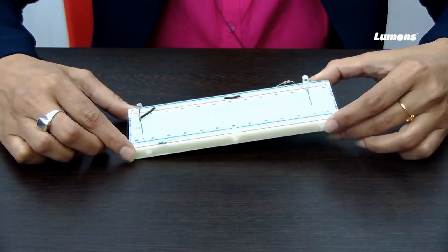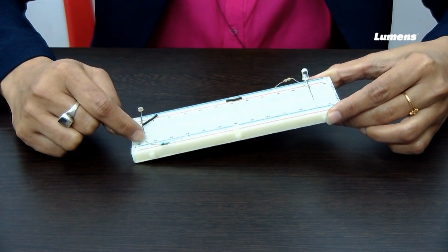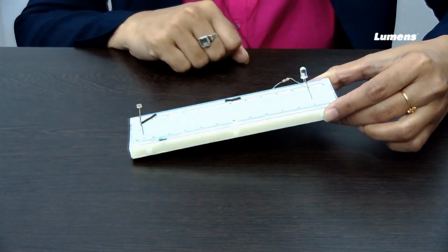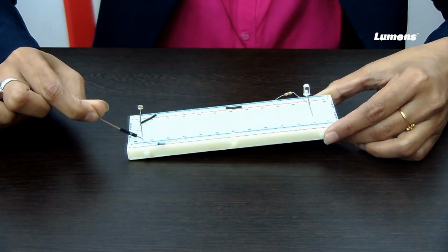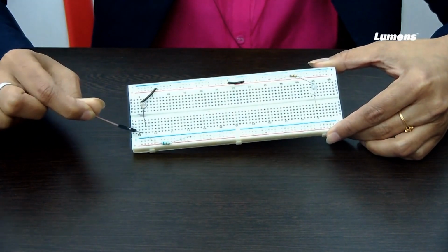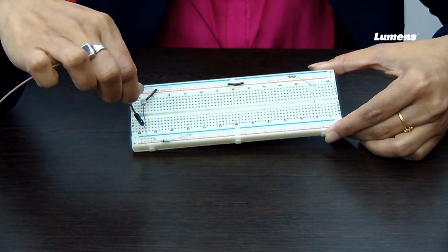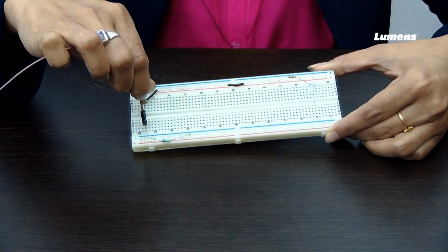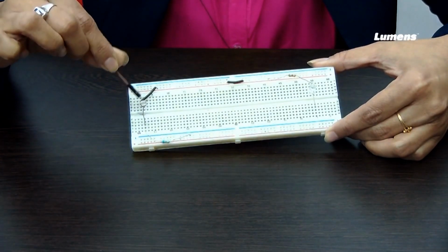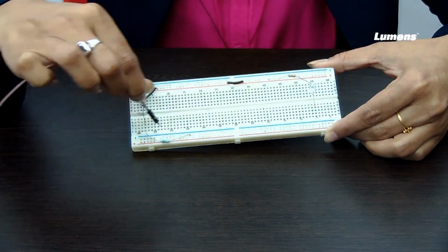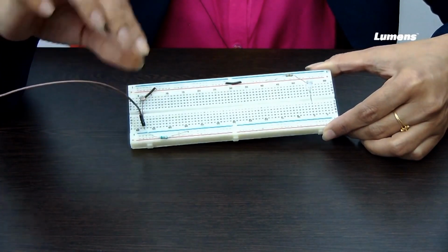This is the LDR. One end of the LDR I will be connecting to VCC. Another end of the LDR, through a resistance, I will be connecting to ground. And please understand from which point: from the point where I am connecting this LDR through this resistance to ground, I will be taking a connection from this point to the analog input. Okay. So, please make this connection clear. Two ends of the LDR: one end I will be connecting to VCC, another end through a resistor I will be connecting to ground, and from this end I will be taking the input to the analog port.